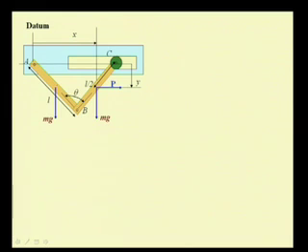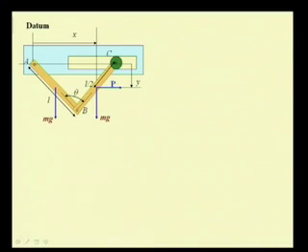We also would like to know the position of the center of mass of this link AB as the system takes a new configuration, because we are interested in computing the work done by these active forces. So, we would like to know the position of action of these forces as this system undergoes displacement.